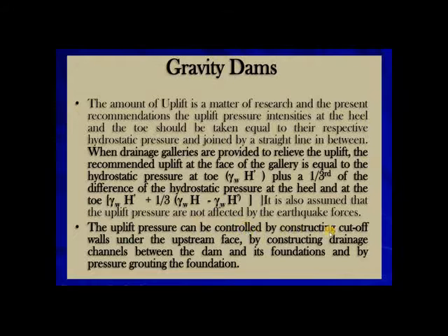The uplift pressure can be controlled by constructing cut-off walls under the upstream face, by constructing drainage galleries, which we discussed, drainage channels between the dam bodies and the foundation, and by pressure grouting the foundations.